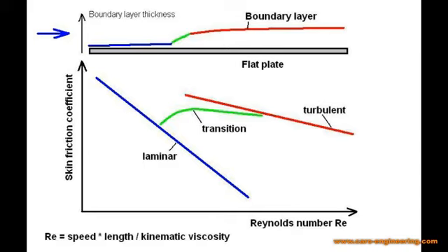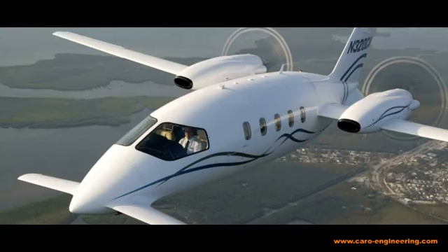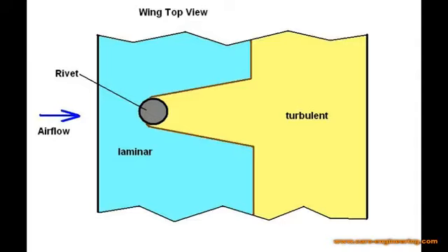For the lowest drag, the boundary layer needs to stay laminar as long as possible to minimize the skin friction drag. The laminar boundary layer is quite stable until the thickest part of the object is reached. It is hard to keep it laminar much beyond that. For that reason, the thickest section of bodies and airfoils is shifted aft as far as practical, where low drag is important during the design stage.